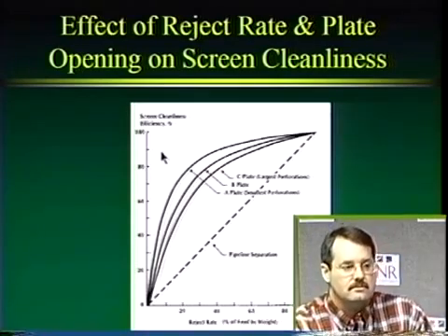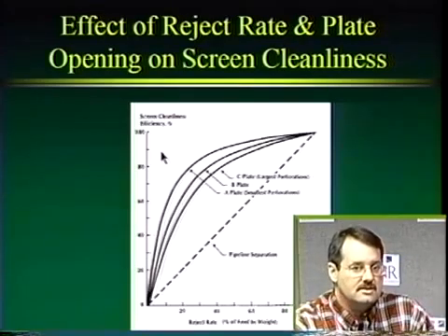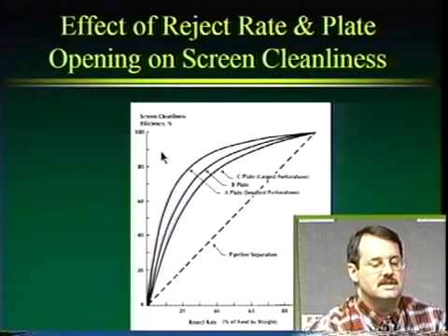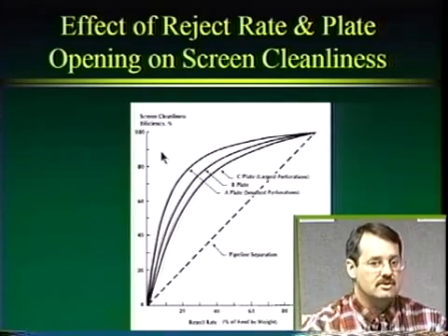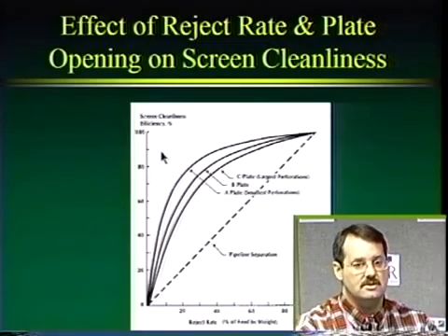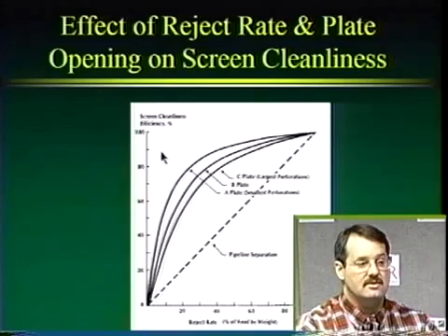Currently, some of the smallest slot sizes are 4-cut or 6-cut. 6-cut is common. 4-cut is pretty rare, but sometimes you'll hear about it. Now, 4-cut is 4/1000ths of an inch, and that's about 100 microns.